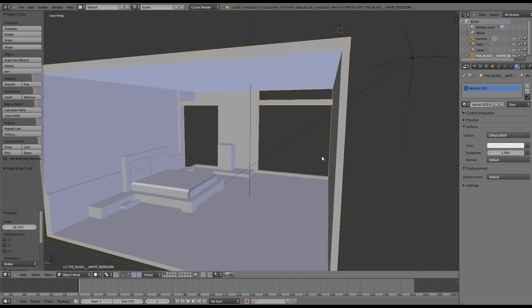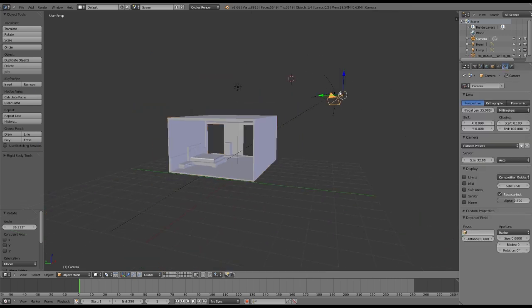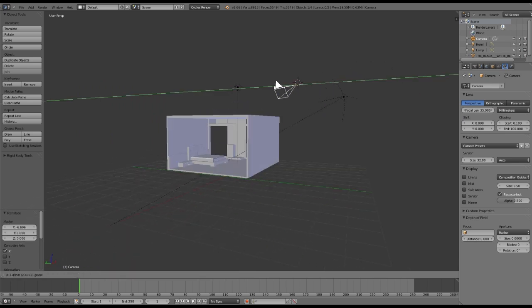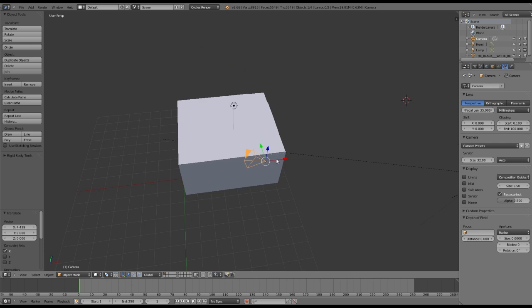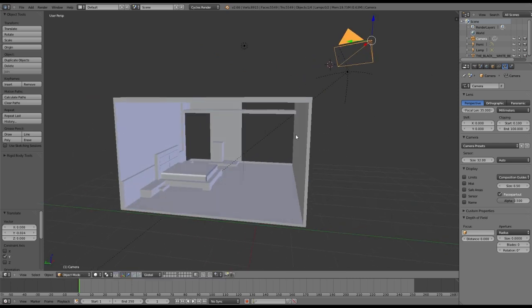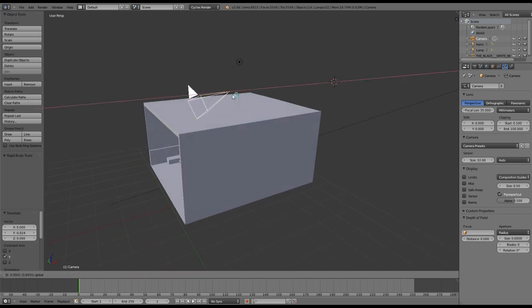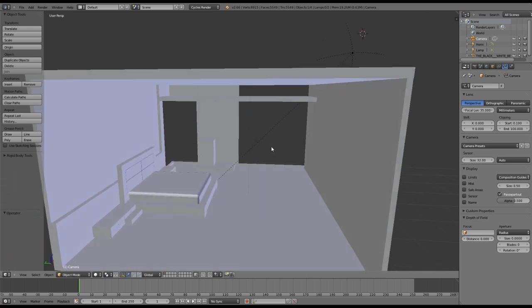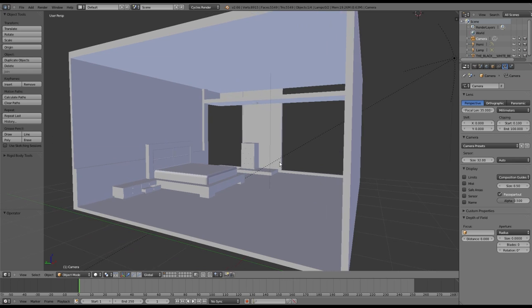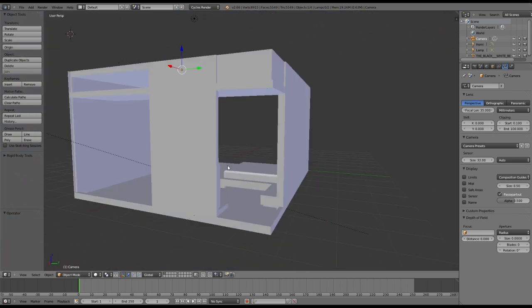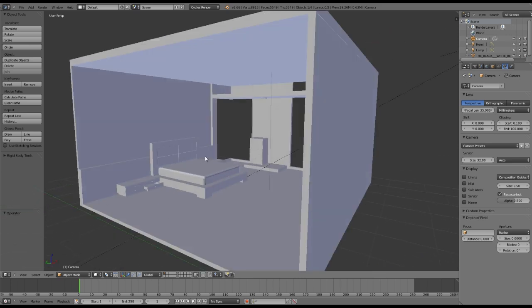Once we've done this, we have our material set up, and all it comes down to now is changing the camera view. Now, as you can see up here, we've got our camera, which we can then move around with these different axis transform tools, these arrows. But we don't want to do that. It's quite a complicated system, and it takes quite a time to do all the orientation for the rotation and make sure it's all correct and check to make sure it works. What we're going to do is we simply find a view we like in our scene, just using our navigation tools on our numpad or our mouse.